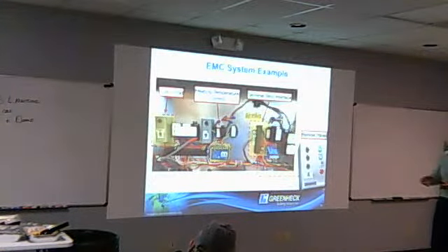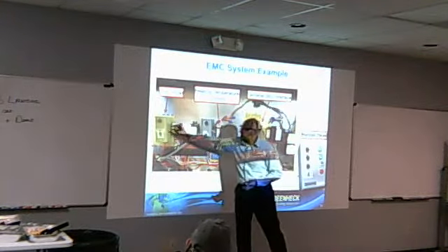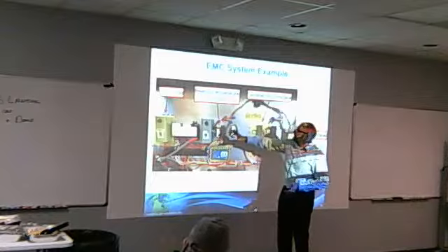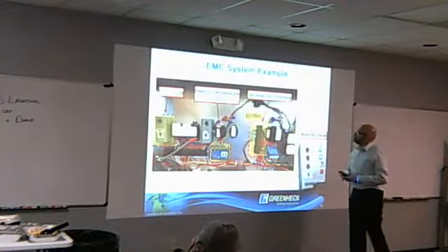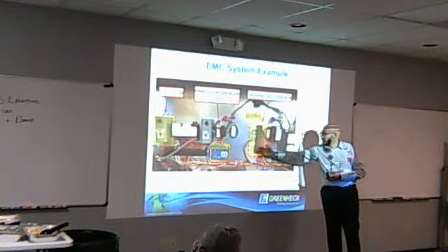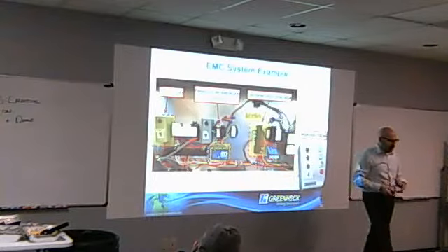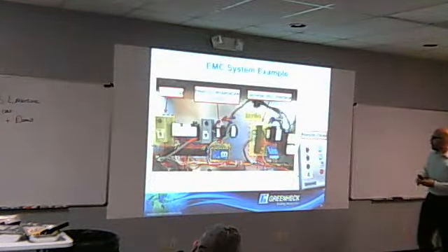So in terms of those EMC systems, you're going to open a cabinet and see a dial for the outside air thermostat. Where do you want that set? You're going to have heating temperature control wired to that max control system. You're going to have a terminal strip interface, so you start landing wires on a terminal strip to operate the fan, not operate the fan, engage heat, disengage heat. You're going to have a remote panel.